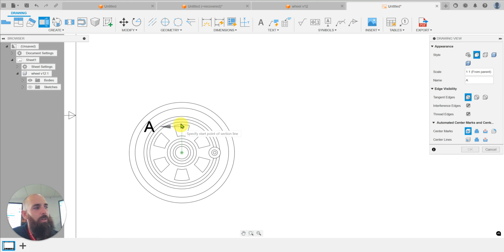And then once I hover there, it'll let me trace it up. It realizes that there's some importance to that center point. So now I can click once straight above it. I'm going to move my mouse down and click another time straight below it. So we've got this vertical cutting plane line. And now it wants me to do a third one, but I don't want that. I just want one cut, so I'll now click the check mark.